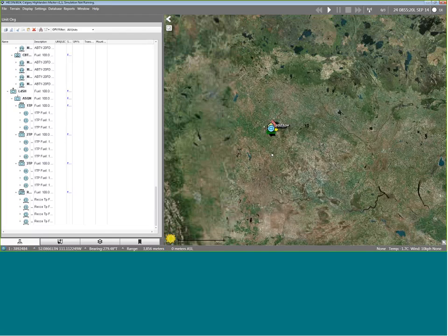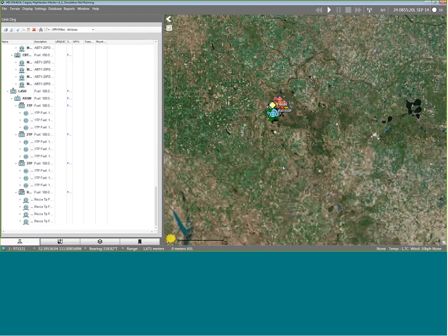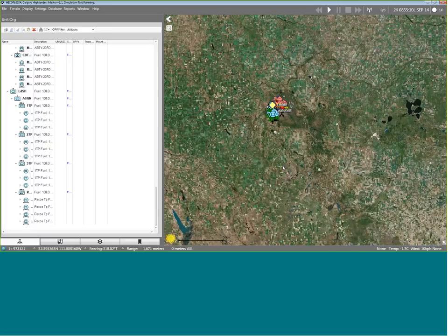And what it means is we can use online imagery, so it's geo-rectified, so it's immediately apparent when we blend it with information coming in from GPS that there's no offset. And there's no requirement for us to have a specific terrain database. We just use the actual imagery, satellite imagery and mapping that's available to you and anybody else.